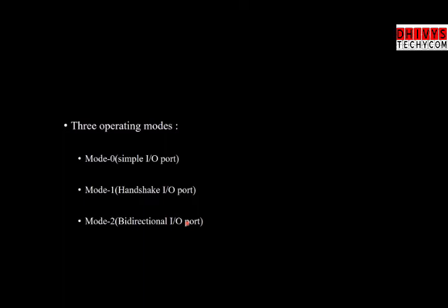That is mode 0. Mode 1 is the handshaking mechanism, an idea everybody will be very aware of, where we want to provide a handshake. Assume one part is a transmitter and the other is a receiver, and it can also be a transceiver at the same time. The first thing is we send an RTS. RTS is nothing but request to send. Are you free? Shall I send the data? If the receiver is found to be free, it will send a clear to send signal.